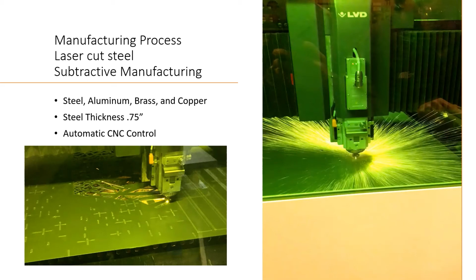So again, maybe not a perfect answer, but there are a few variables to look at as you are cutting away and using a laser cutter. I would say the first is, what is the percentage that you're trying to cut away from the actual base piece? And within that, are there channels or sections along the sides or down the center where you can hide structural elements that you wouldn't necessarily even notice? Further down, if you are cutting away a lot of pattern, can you weld in or add additional support elements at a later process, using transformative methods to provide rigidity to make sure there's enough structure there? And then all of this typically is going to be tested.